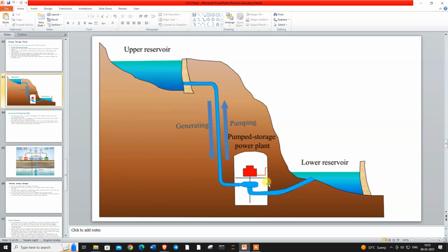and then we are going to use a small hydroelectric power plant, which consists of the turbines and generator. And then the penstock is inside the crust of the earth at that time, and here we are going to use this pumped storage hydro power plant for both purposes. First of all, we are going to use the water in the upper reservoir for the generation of electricity with the help of gravitational force. And secondly, the water which is available at the lower reservoir, which has been collected after the turbine, can also be pumped back to the upper reservoir. So this cycle continues, and this is why we can call it an energy storage power plant.